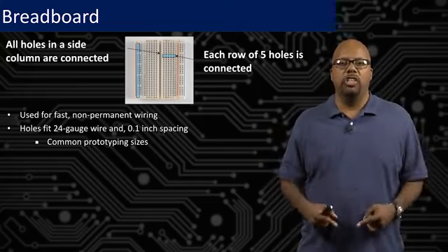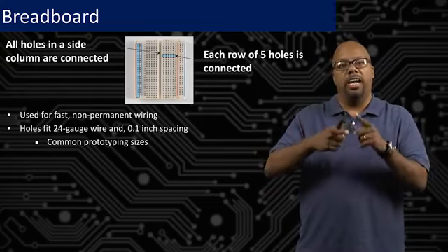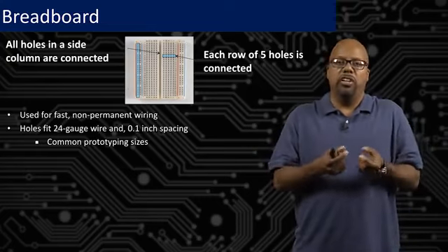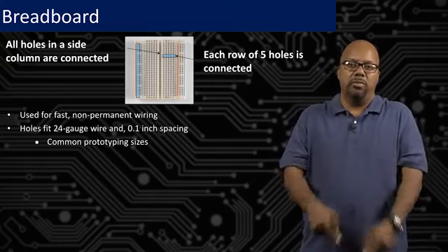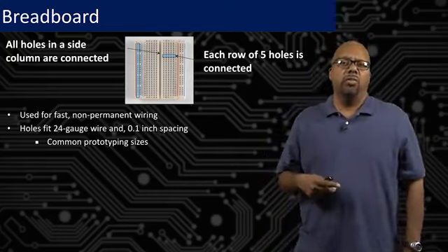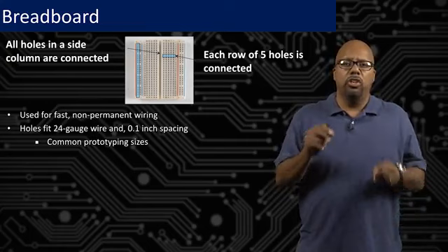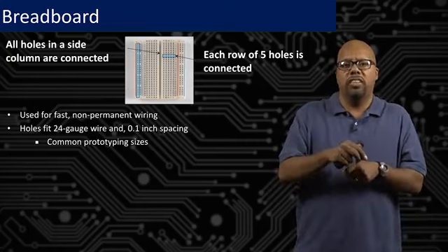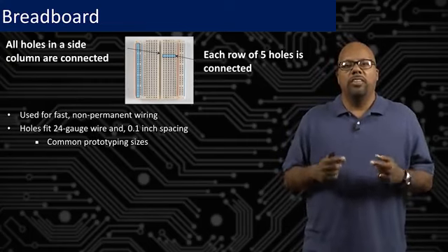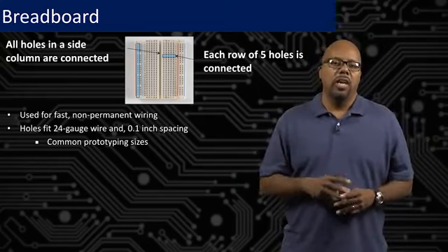Soldering is a more permanent connection, where you take two pieces of wire, two pieces of metal, you want to connect, you take a hot iron, touch it to the joint, you bring some solder, which is softer metal, you melt it onto the joint and it forms a seal and it connects them electrically. We won't do soldering because it's more permanent, and we're just prototyping. You're going to be trying things, making mistakes, trying again. So soldering is too time-consuming. In the end, when you know everything works, then you might solder things together. But we're not in that mode.